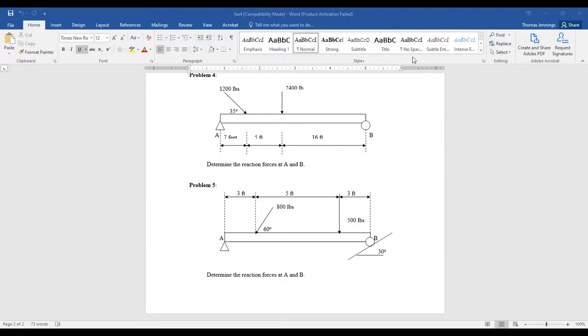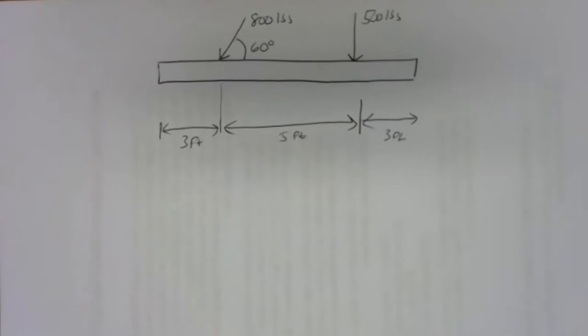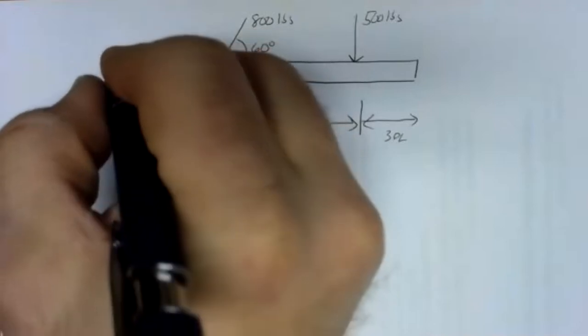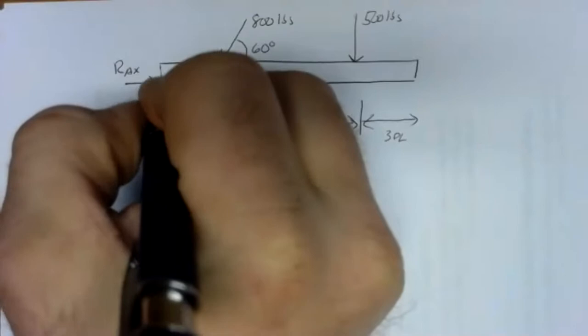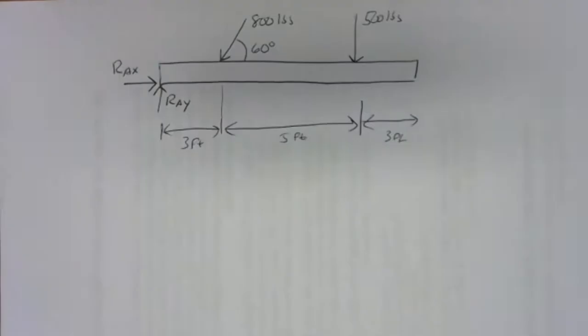Great. Prime number for the length of our beam. That always makes for nice numbers. So there's at least part of the free body diagram. The part I haven't included yet are the supports. Now the pin support, it should be pretty old habit by now to just replace that with 2 perpendicular forces. I'm going to call those RAX and RAY. The support at B should have been the point that was a little bit harder to figure out.